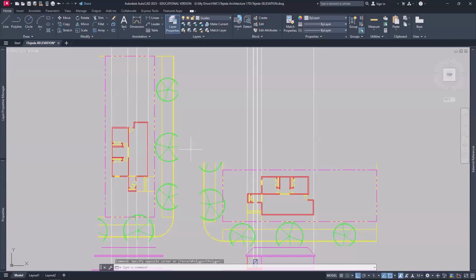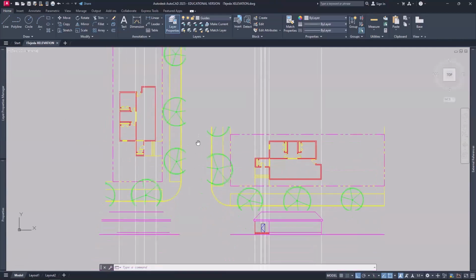All right, so if there are no questions, make sure you control save. So control S, and then keep making progress. When you're all set, make sure you close the elevation file and then close out. And then if needed, as you start generating the elevations, you decide that you want to maybe put the windows in different locations. There's still time to do that. As long as all of your windows and door locations match on your AutoCAD drawing, you're going to be fine.